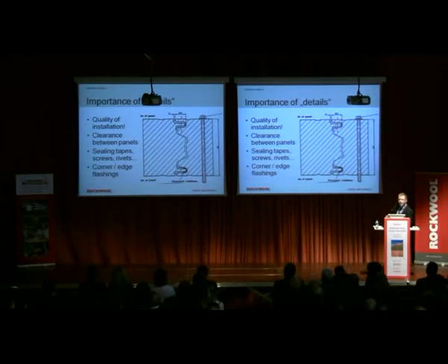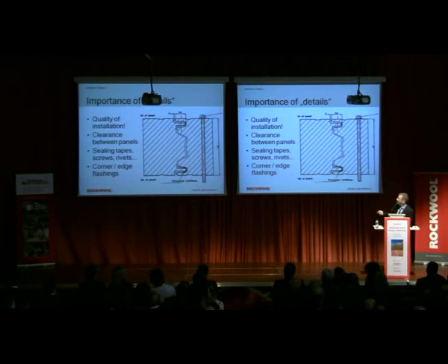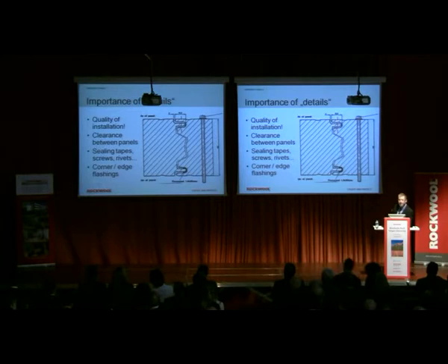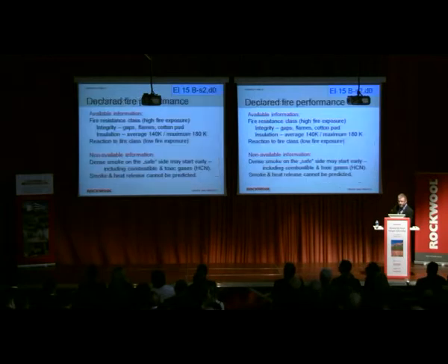If they were part of the tested specimen, they have to be installed on site, although investors don't like these screws and rivets. But they are very important, believe me. If you don't use them, you can experience much less fire resistance. So these are very small details which all people involved in a building process should be aware of. These small details are there because of fire safety.